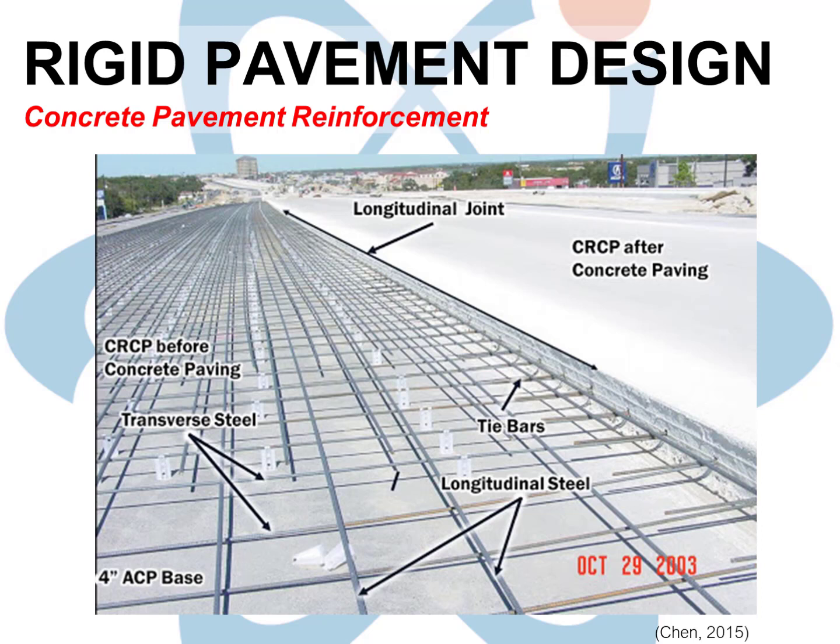Crews must use torches or other means to cut apart the steel holding together the shattered sections of concrete, a process that is dangerous and very time-consuming and expensive. It also renders the demolished concrete unfit for reuse, and it must all be thrown away. Unreinforced concrete is amenable to quick demolition, and the demolished concrete can be run through a crusher with the resulting material reused in new concrete or in the design and construction of base and subbase layers.